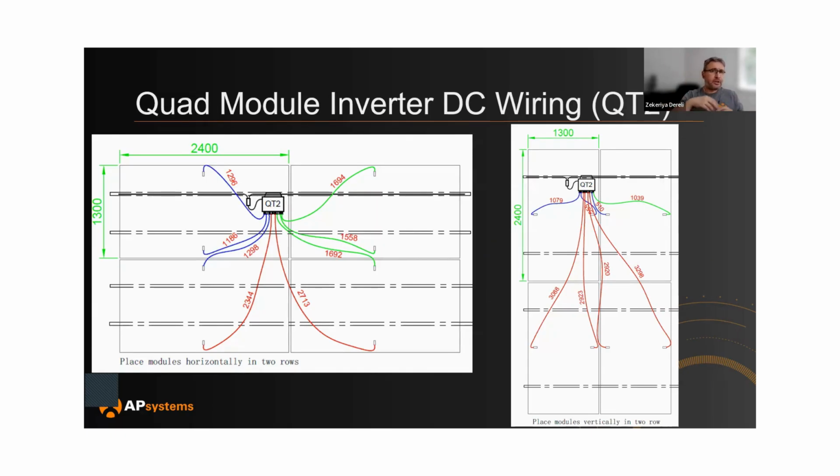Now, modules have a certain length of PV cable, right? From my experience, most of the time they have a shorter cable, like 10 inches or so. Some of them have about 50-ish inches, like 1.2 meters. It's always good to go with a module that has longer PV cables, but even that is not going to reach your microinverter all the time.